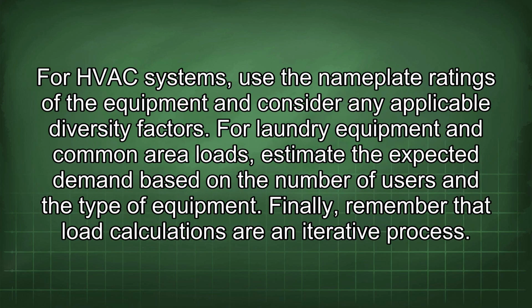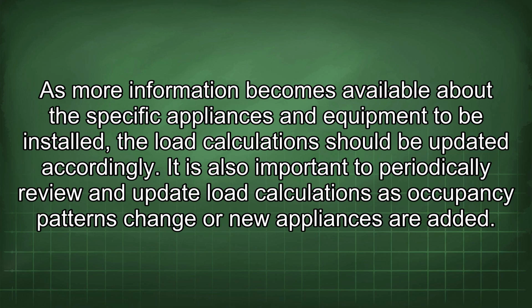For HVAC systems, use the nameplate ratings of the equipment and consider any applicable diversity factors. For laundry equipment and common area loads, estimate the expected demand based on the number of users and the type of equipment. Finally, remember that load calculations are an iterative process. As more information becomes available about the specific appliances and equipment to be installed, the load calculation should be updated